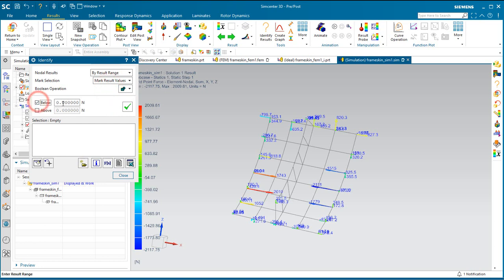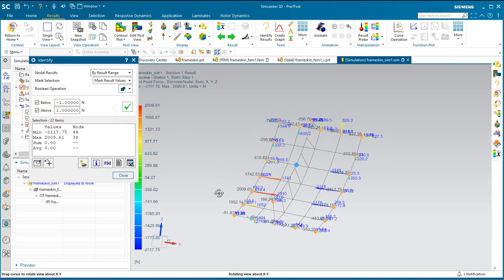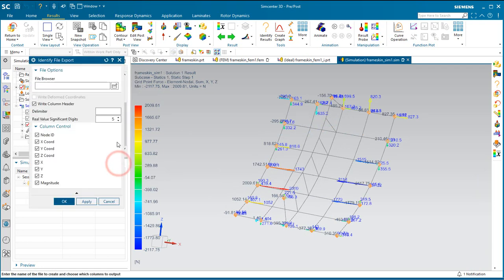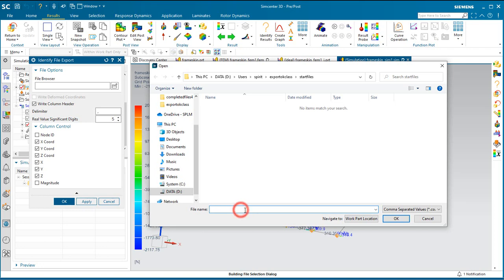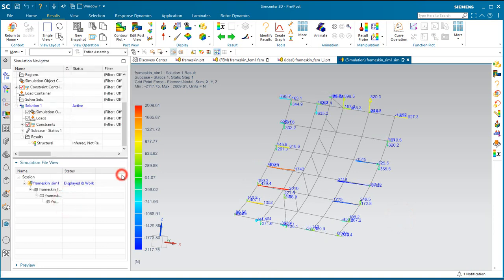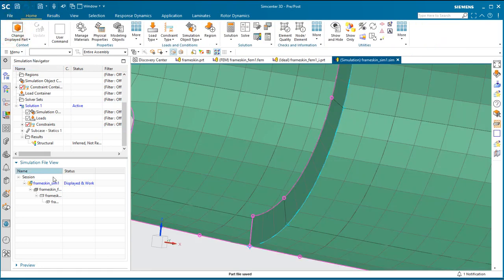All right, so there's a number of ways that we can grab those nodes around the perimeter. Basically, they're all the non-zero results. Everywhere else, the sum of the grid point forces is going to be 0 along the rest of the model, except on the perimeter, so I'll go for those non-zero results. And I want to write them out to a file, the XYZ location and the XYZ force. We'll use a comma delimiter. We'll write it out to a file called XYZF. And we'll use that in just a moment for our fine grid breakout model.